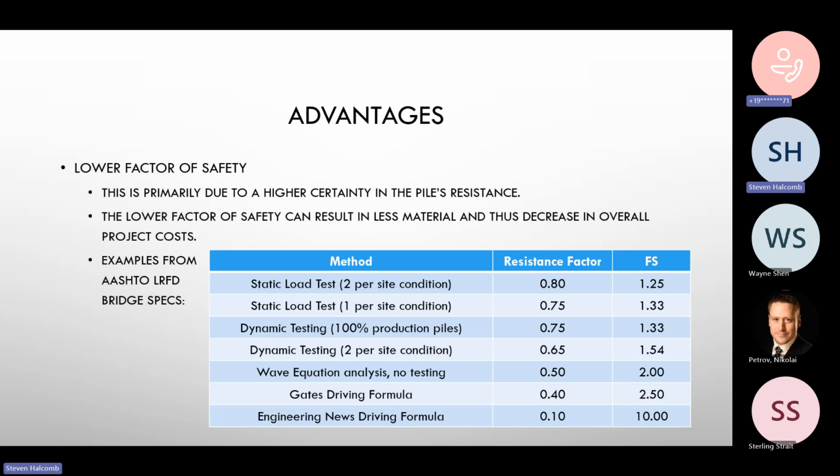Are there limitations on pile size or pile length that come into play to be able to use this? Like if you have a 400-foot long stick, is it still working? To the best of my knowledge, yes. I mean, it still just treats it as a one-dimensional rod. Sizing the hammer for that much capacity would probably be the tricky part of that.